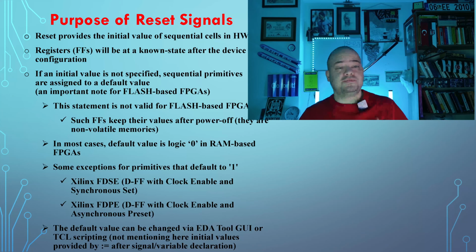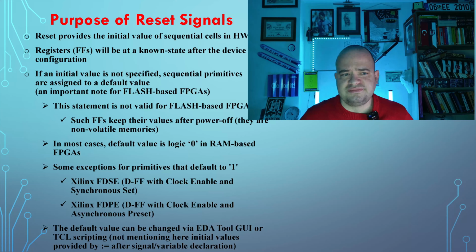Okay, the first one was the purpose of reset signals. So as we discussed last Wednesday, reset provides the initial value of sequential cells in hardware. So registers, in other words flip-flops, will be at known states after the device configuration. So this is what reset usages provide us.